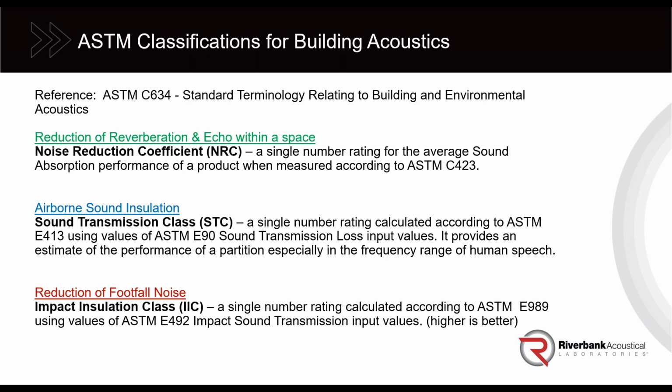As you're beginning your journey in acoustics, it is intuitive that all these things might be similar, and that the properties of materials that are good for one must be good for the other, right? And that they're somewhat interchangeable. Very wrong. In some ways they're often opposite. Different types of materials are sometimes good with NRC and bad with STC, or may have a good STC but a poor IIC.